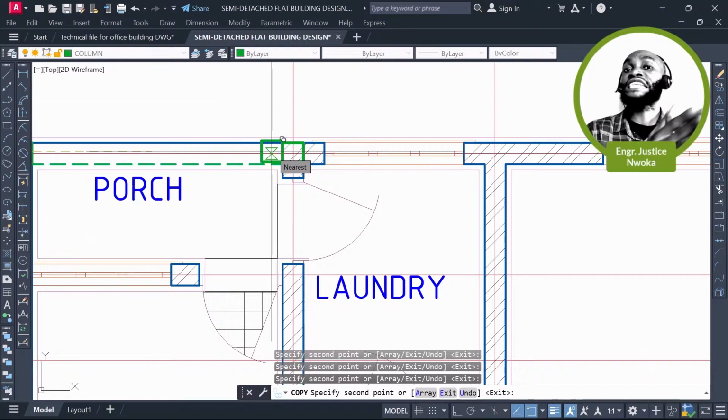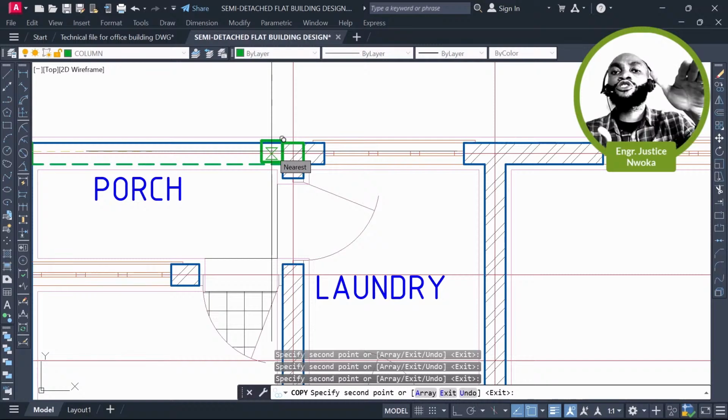But when you go to 7 meters, going beyond the normal just means you are wasting the client's money, because you will have a bigger diameter of reinforcement like Y20, and a big section of concrete for the beams and all that. So don't do that. Just keep yourself below that.